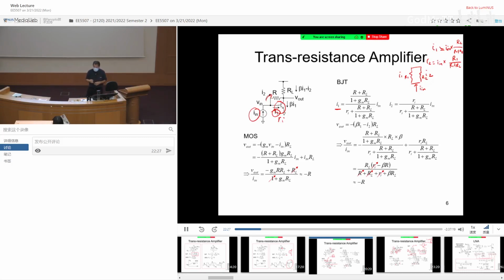If you want the current going through the I2 branch, you just have to figure out the equivalent resistor in the I1 branch, which is Ri. So that is exactly what we are doing. The total resistor is Ri plus the resistor that we derived, which is the resistor in the I2 branch. And since I'm obtaining I1, I take the resistor at the I2 branch. This is the I2 branch resistor.